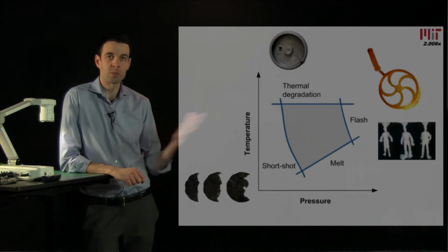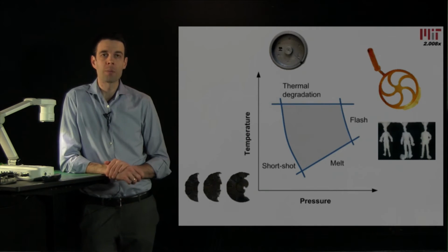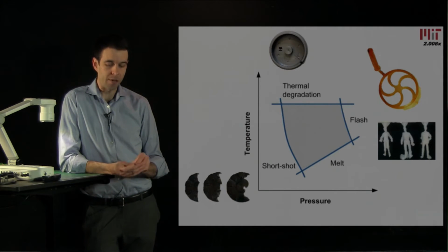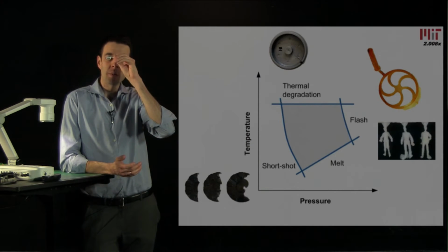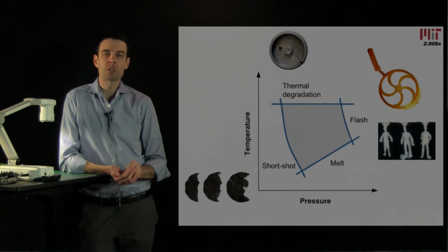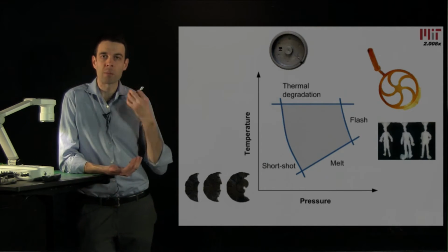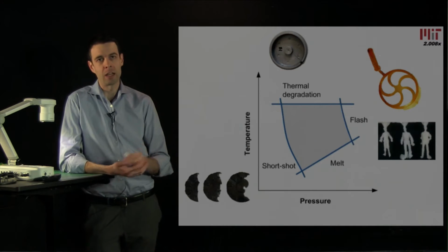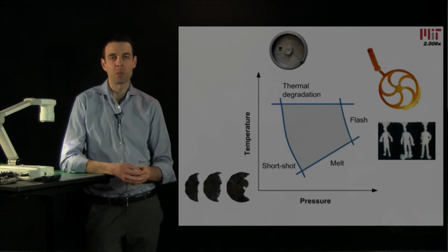And I could argue that this part could have been made better with higher quality, but given the small size of the mold cavities, I mean, gee, they're a millimeter wide or so, and the intricate features, it was probably pretty hard to get the plastic into those small cavities and eliminate flash. So that's what the part ended up looking like.